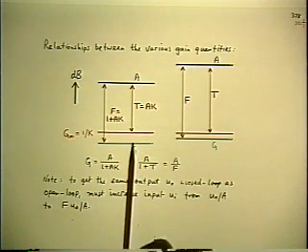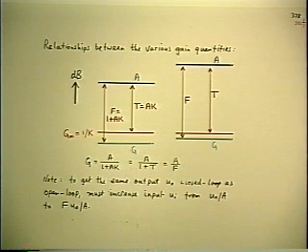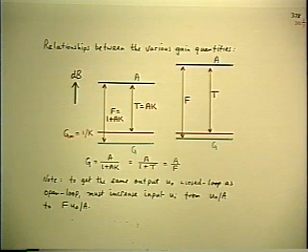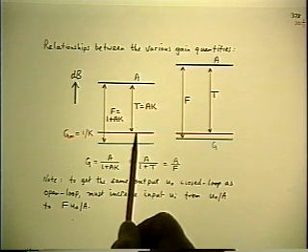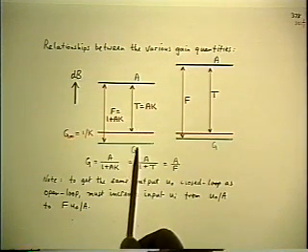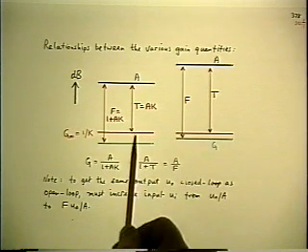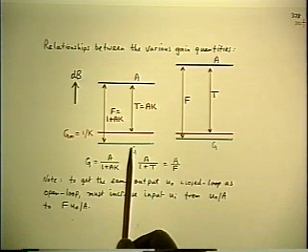What is the number of dB between the red line and the green line? What quantity does that represent in dB? Yeah, D, the discrepancy factor. This additional parameter that you have to worry about all the time. D is the discrepancy between G infinity and G. And in dB, it's the vertical displacement on the dB axis between those two quantities.